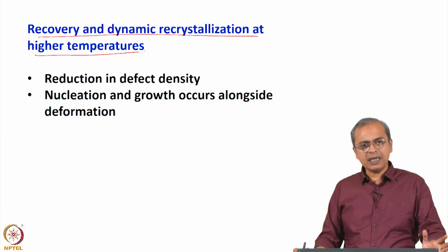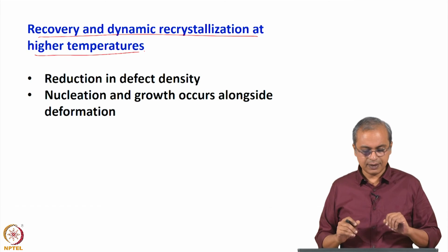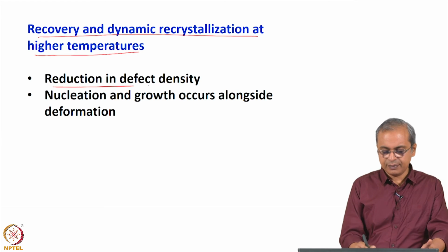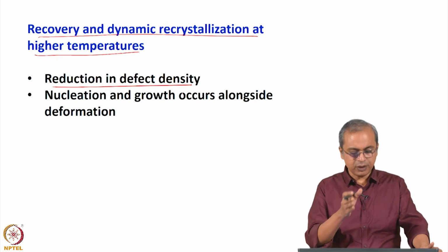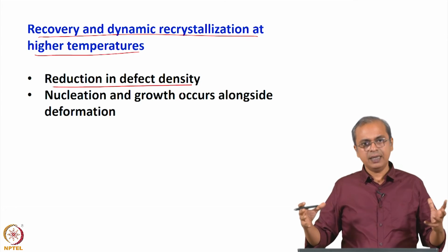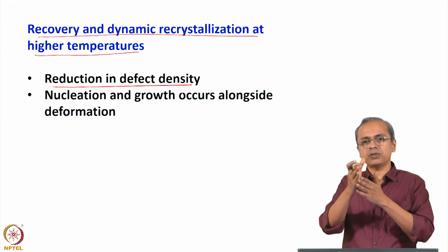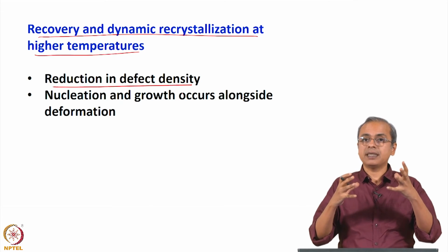So recovery is a phenomenon in materials which is primarily associated with a reduction in defect density. So what is this defect? Defects are all those dislocations that have been formed in the material. So you are deforming that material, and so dislocations, or planes of atoms which are moving, or half planes of atoms which are moving, have now formed in that material.